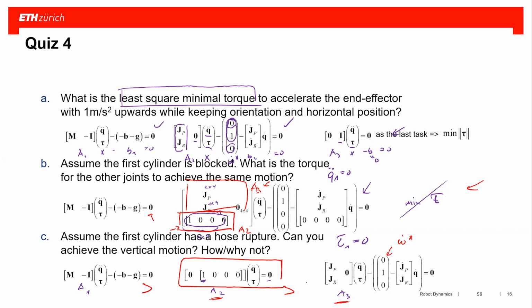Although the dimensionality of the joint space is 4-dimensional, with these 3 actuator inputs, we have full authority of locally controlling the 3 end effector accelerations for a certain time period. If you want to fully control the system over a longer time period, you would have to have an MPC controller which takes into account time evolution of that.